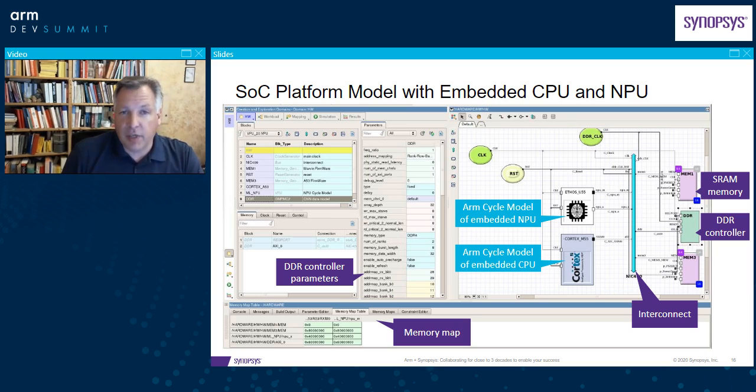The interconnect system and the memory subsystem shall be capable of providing the data at the right pace. And for this tailoring and optimization, you need good performance models for the interconnect and memory and other models as well. And that is all provided by Platform Architect out of the box. Different SystemC TLM models of interconnects, memories, processors.